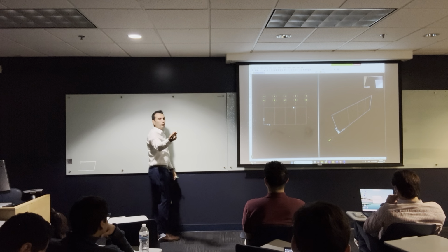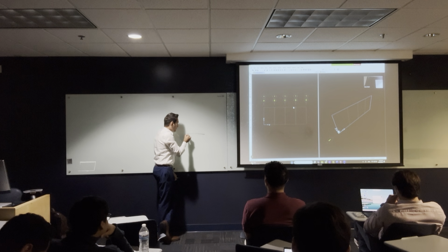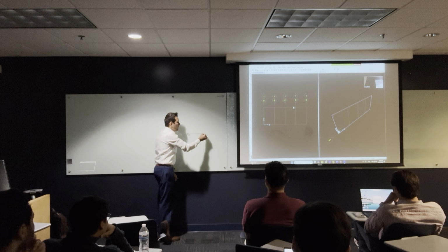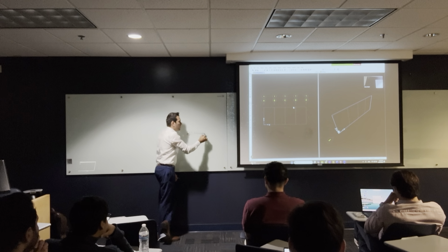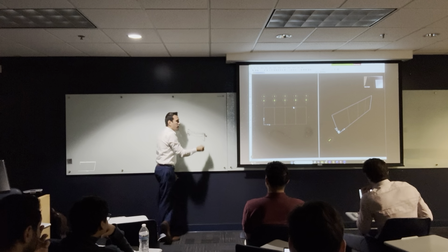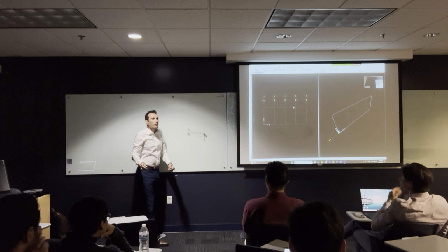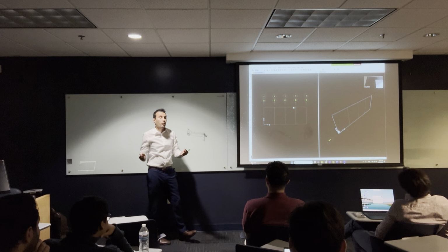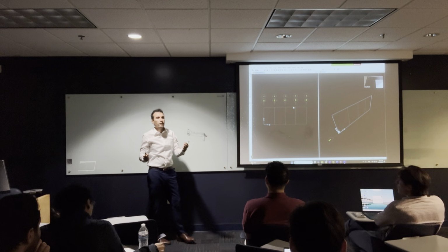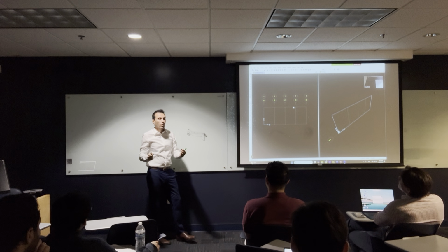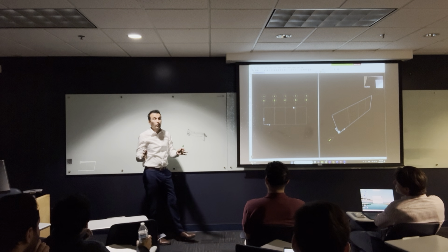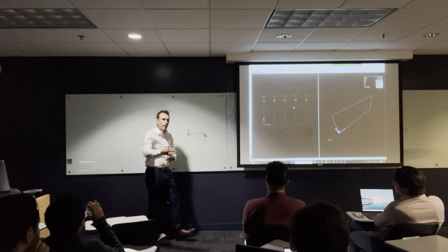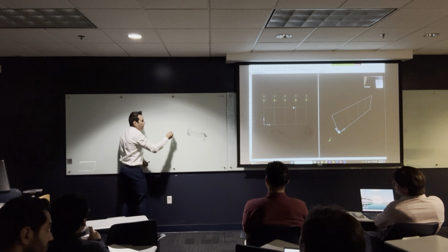So when we do a structure analysis, all I'm interested in, if a beam has a load like this, is the bending moment. I'm interested in the shear force diagram on this beam. So frame is enough to give me all that. But frame is not the most accurate representation of the beam. We are eliminating a lot of information about the beam. So when we do research and we want to investigate a lot of stresses and strains and cracking, we model this frame as a shell.